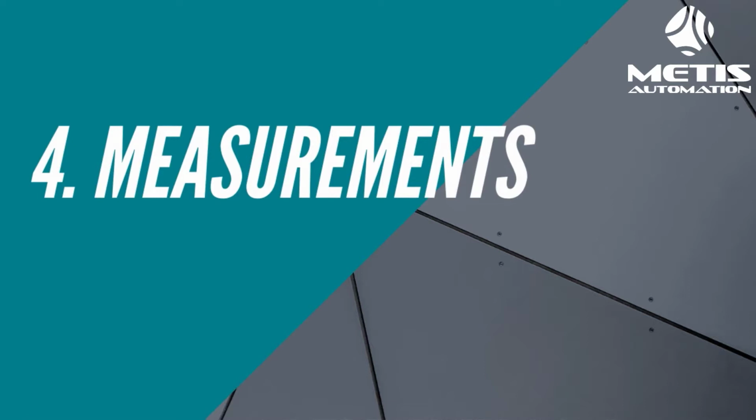Number 4 is to identify some measurements that will be signifiers of low variation in your products. So it could be measuring diameters, sizes, electrical measurements, surface finishes, things like that. What are the key measurements that you could take during the process to signify whether your process is under control or not? Sometimes this is called statistical process control. If you trend the performance within an upper and a lower limit, if you see the trend going towards one of the extremes, you know that something's happening to push that process towards higher variation, and it's a trigger to go and do something about it.